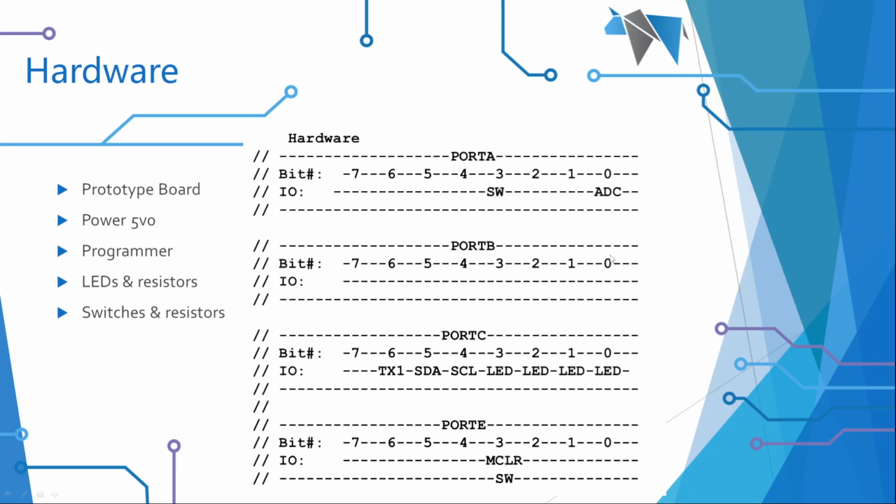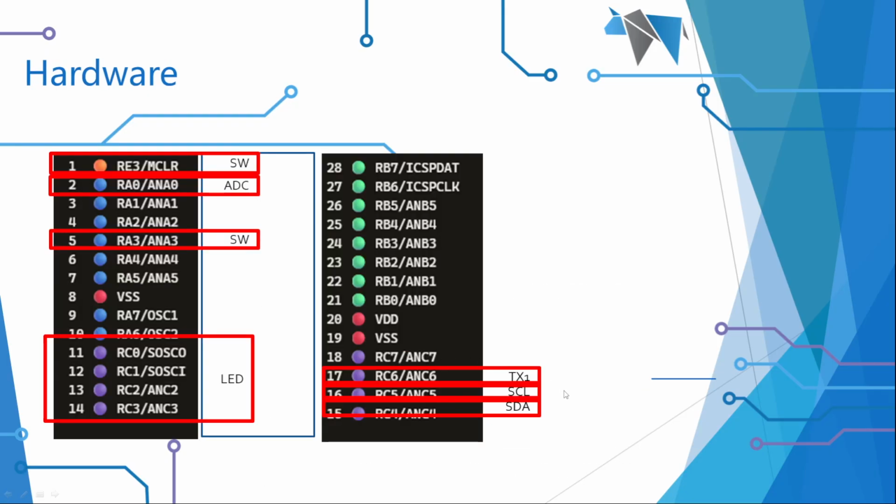And the hardware, in terms of the chip itself, I'm going to attach to port C. I'm going to attach the SDA, that's the data line, to 5, and the clock line or SCL to 4. And so it looks like this. I've got two new connections in this little diagram I've been maintaining. The clock's here and the data line's there. What does that look like on my prototype board? Well, the prototype board's got a bit busier.